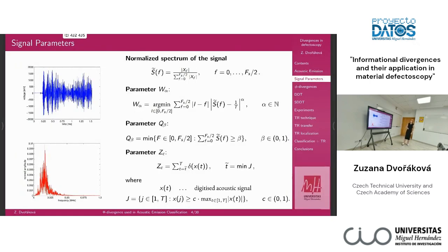Here you have an example of a typical acoustic emission. This is the so-called pen test. It's really useful. We use this test on almost every material. It's a pencil breakage on the material, the pen test. We can measure it by sensors, and the signal looks like this.